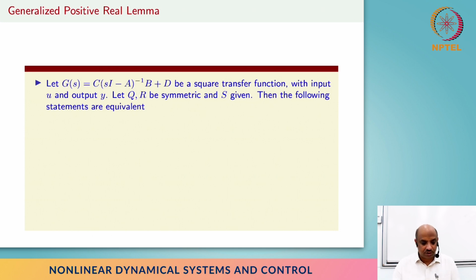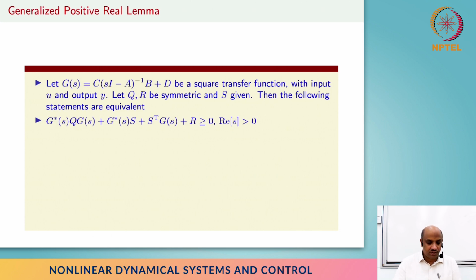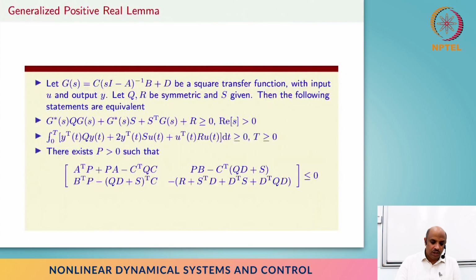So some of the robust control analysis results can include disturbance rejection through the introduction of an artificial uncertainty. Anyway, all these things can be generalized in the following result, which says something like, if this particular condition is true, and we're not naming it, but if you want, we can call it G is generalized positive real, if this is satisfied for some matrices Q, R, and S, then we have the following condition on Y and U, and a corresponding LMI, right?